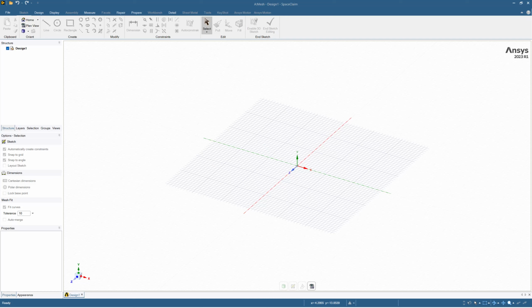In this environment now we will look into the modeling. For starting it, we will have the y-axis along the height of the cell, and starting from the origin we will have the xz plane. From the origin we'll start our rectangular geometry of the cell. On top we will model the cathode because it is very thin, and below, in the negative y direction, we will model the anode side.